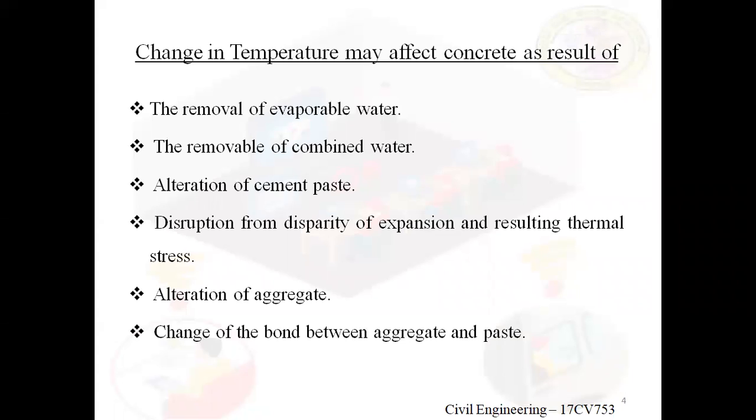Next, alteration of aggregate. Similarly, it changes the bond between aggregate and paste. As I said, due to this temperature variation, the bonding strength will reduce between the aggregate and the cement paste.